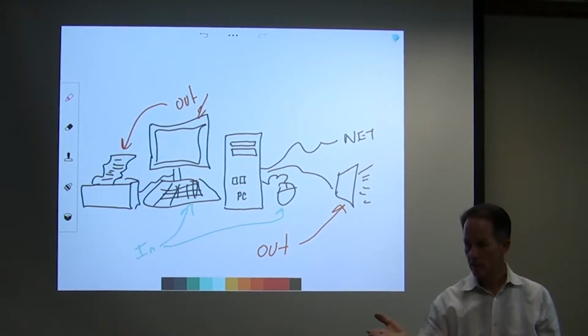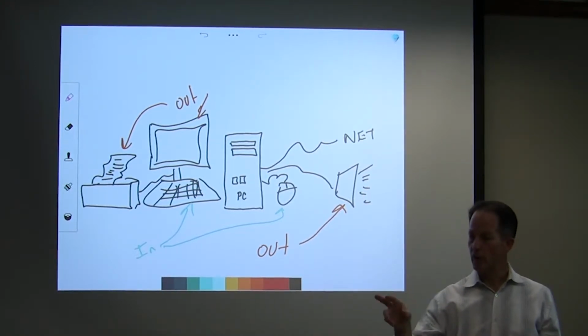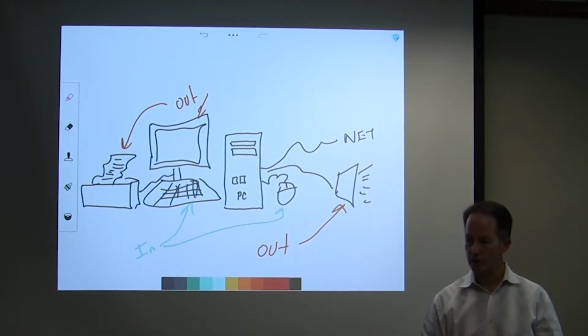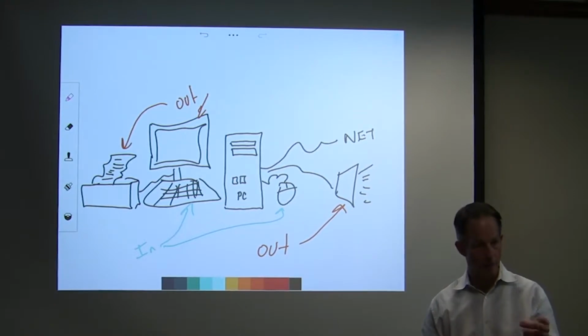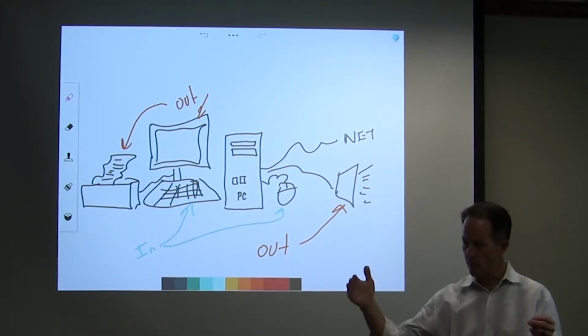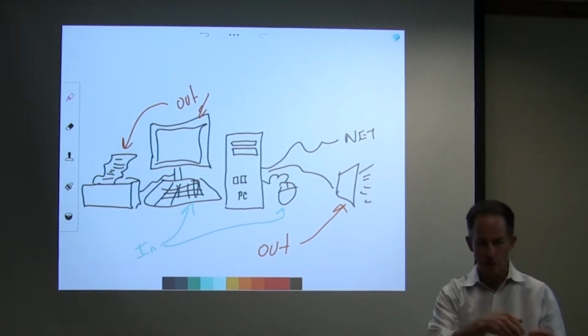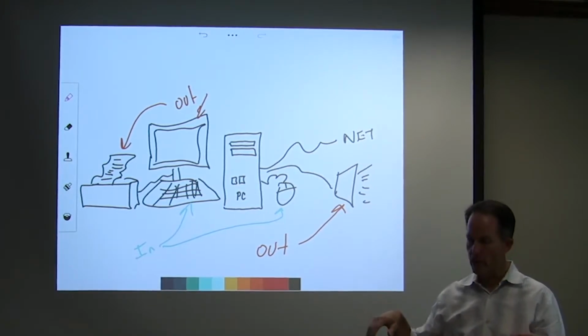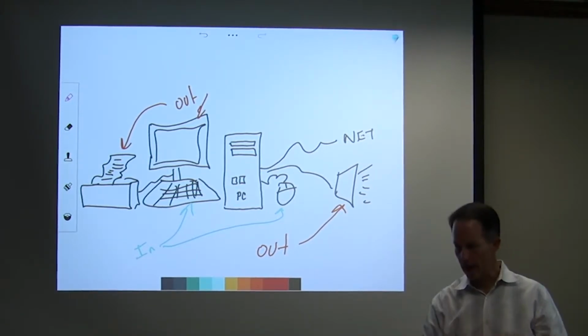It's gonna be either open or closed, on or off. Okay, so voltage or non-voltage. There are different types of outputs. Some are a contact closure, right? That means we bring power from somewhere else into it and then it goes back out if it closes. That's a dry contact.